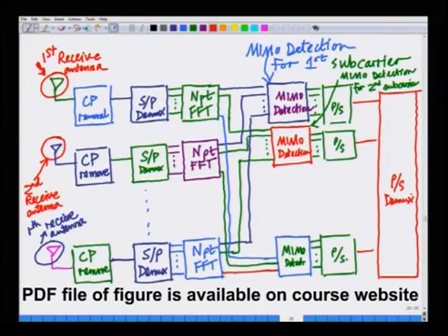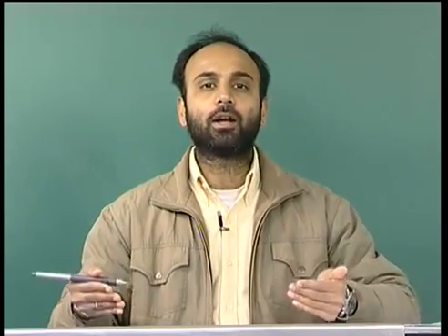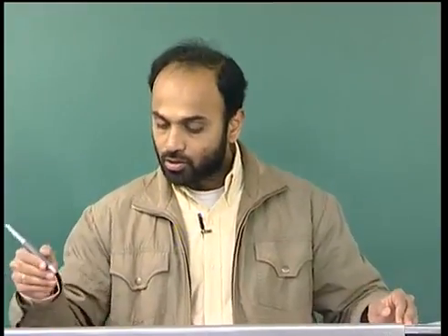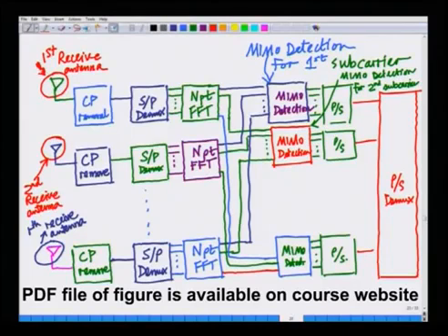That is, you have a block for all the transmit antennas, you convert that into serial at each subcarrier, and then finally you take all these streams from the different subcarriers and multiplex them into one complete stream that can now be used as information by the higher layers or the applications. Okay. So, this is the complete MIMO receiver schematic, which looks slightly complicated, but